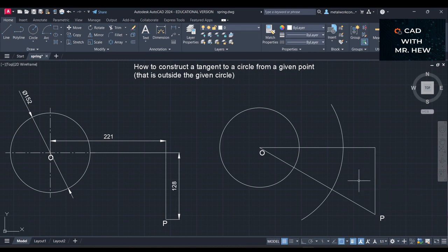The radius would be greater than half the length of the line. You don't have to measure it, you just look at it and estimate where halfway would be. You wouldn't say eyeball the distance, you would say estimate. Draw an arc greater than half the distance.